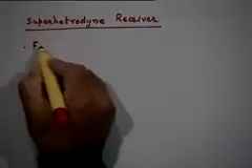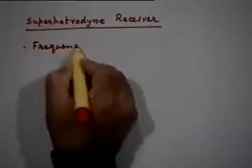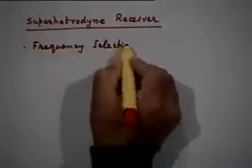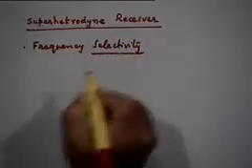First thing is that it should be frequency selective, right. That is basically what is meant by tuning. But more importantly, what is meant by this term is that if there are two transmitting stations at close by carrier frequencies, I should be able to reject one and accept the other. I should be able to accept one without having interference from the closely spaced frequency, right. So, it should be frequency selective enough to reject a close carrier frequency, right. Selectivity therefore is one very important criterion in receiver design.